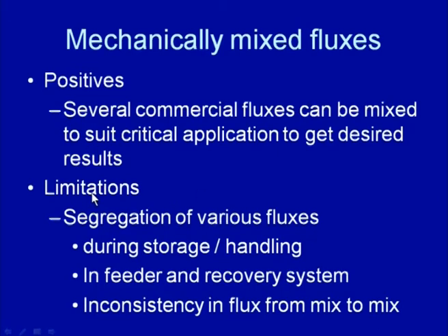But the limitation with these fluxes is that the fine particles or the various constituents tend to segregate during the storage or handling in the feeder and recovery system, and therefore, sometimes inconsistency in flux from mix to mix is obtained.